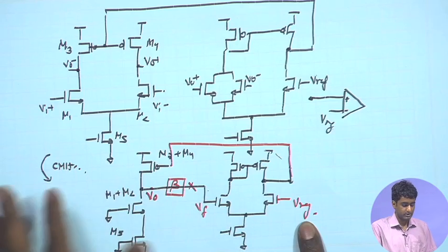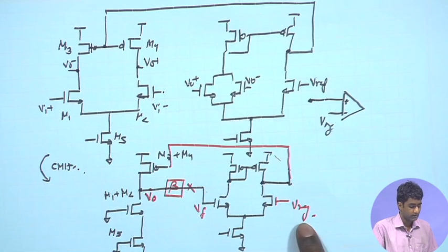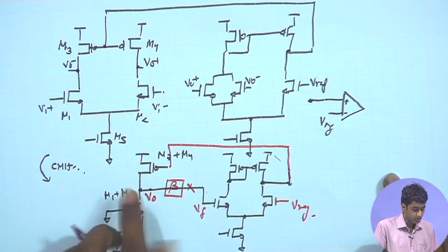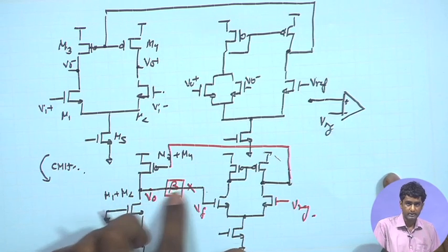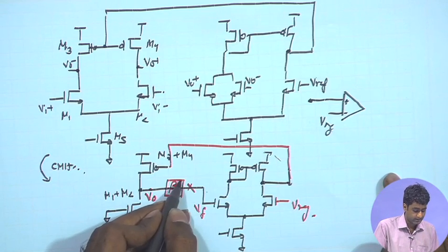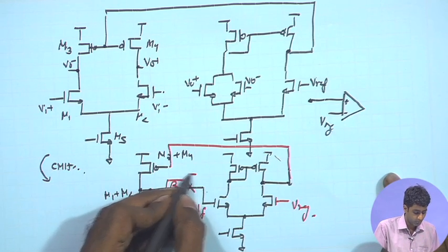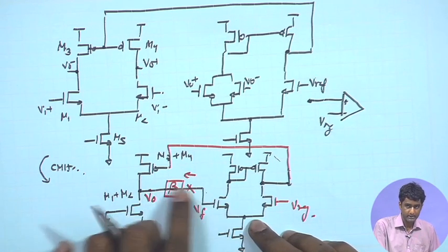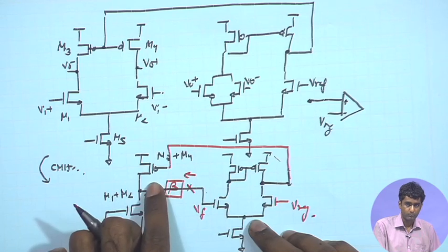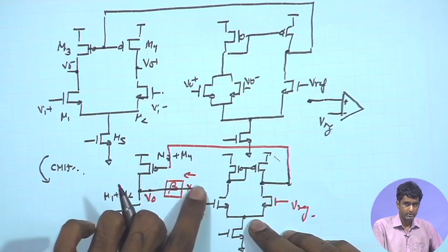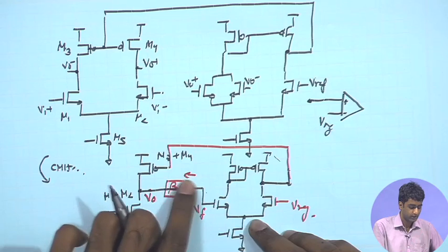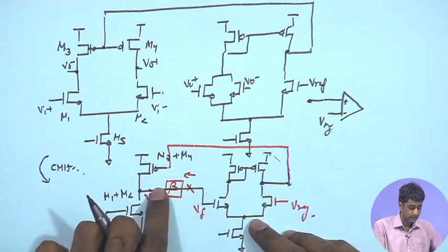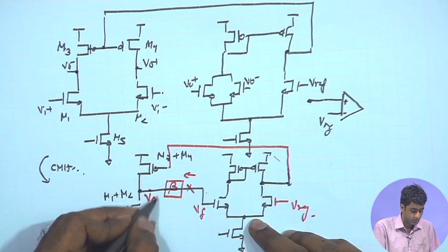Therefore, you have a shunt connection at the output, therefore, we have a series shunt configuration, and while opening the loop for a series shunt configuration, we can see that for the beta network over here, if you are looking at the output port of the feedback network, the configuration is shunt, and therefore, we will be applying an overall ground terminal over here.